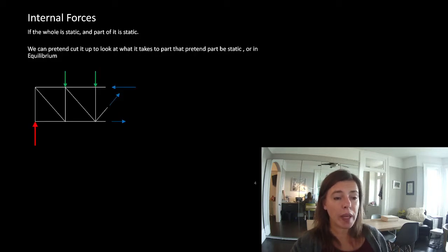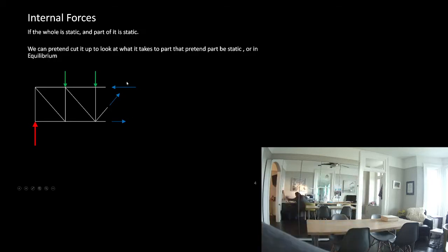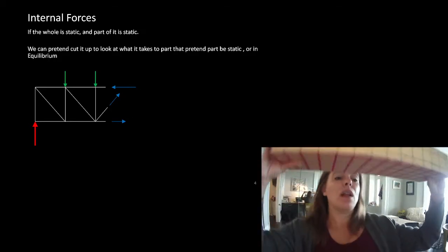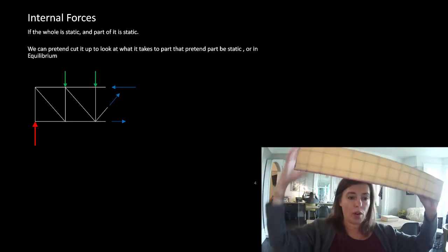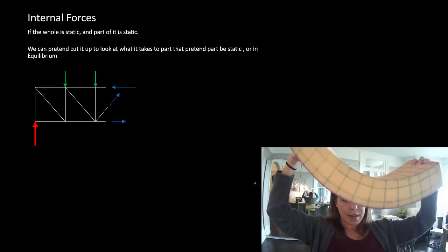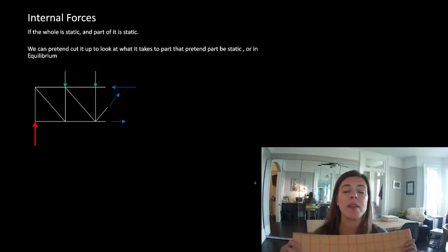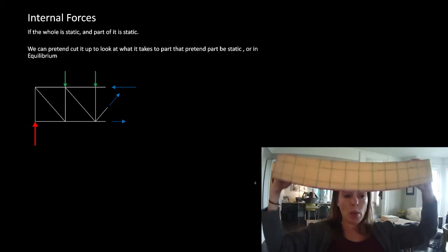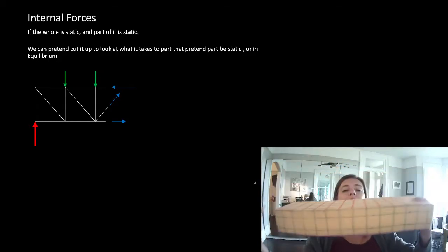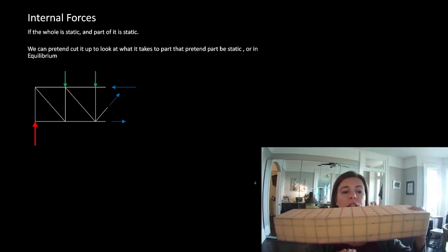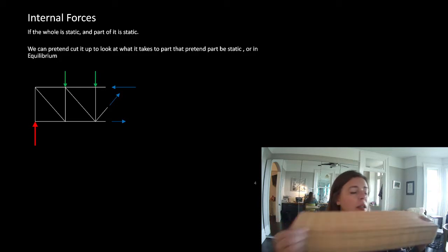So last week, we solved for some trusses, and we found that if we had loads pushing downward on an object, it would bend like this. And we used method of sections to find out what the internal axial components were. Now, we know that if something's bending like this, the top chord's in compression and the bottom is in tension.